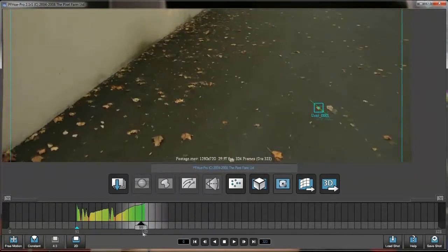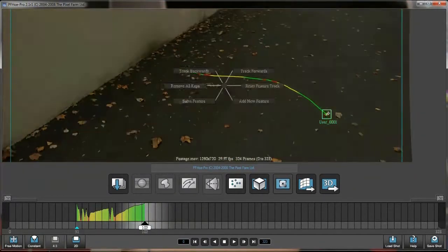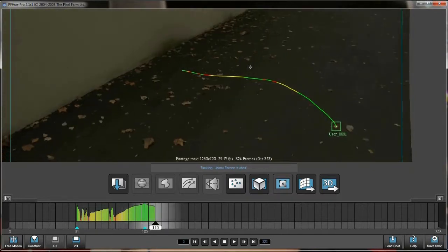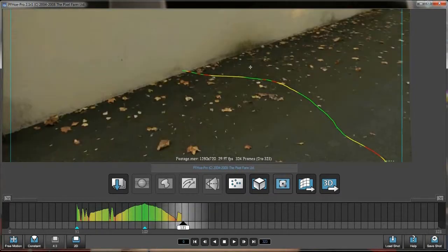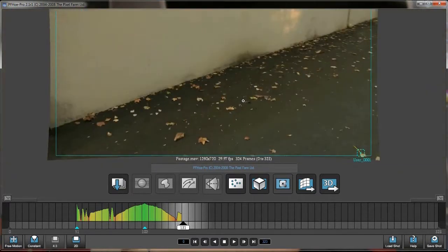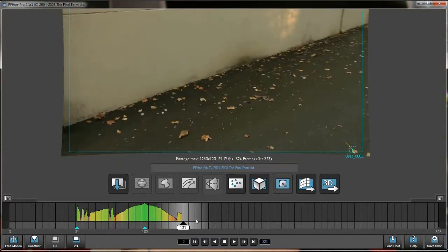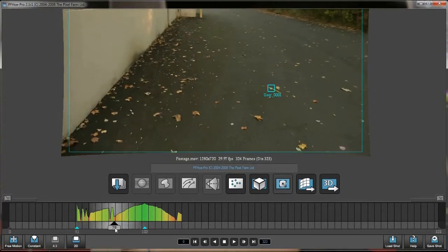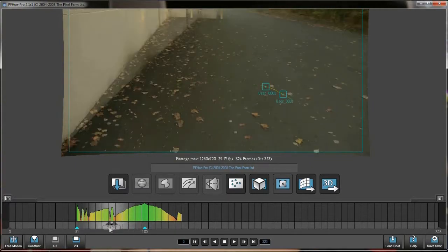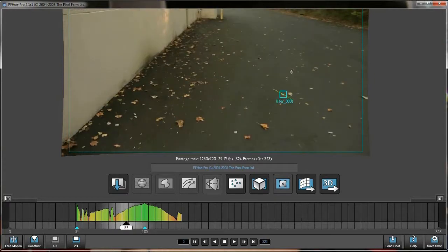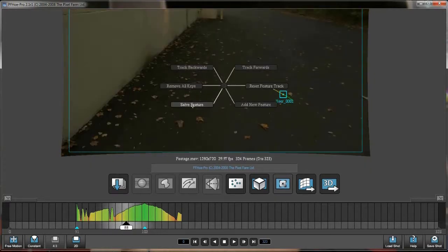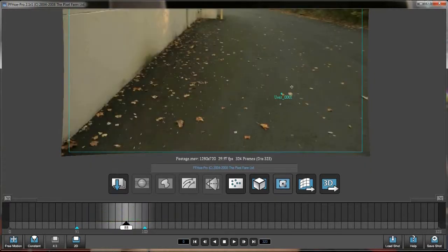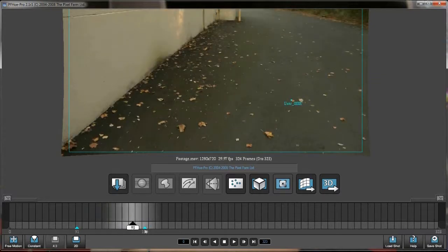Okay, well, let's go back to where we started, and then we'll do the same thing, space, and we'll track forward. And it should end, yeah, right at the end of the shot. Okay, and I can back it out to show you that it's the end of the shot. So we have one point that we've told it to track specifically. Well, now, since we're confident with that, it looks like it's pretty spot on, what we can do is hold space and click solve feature. And what that does is it puts a marker where our track was. It's from this point to that point.